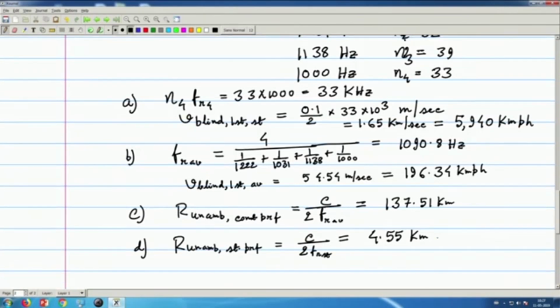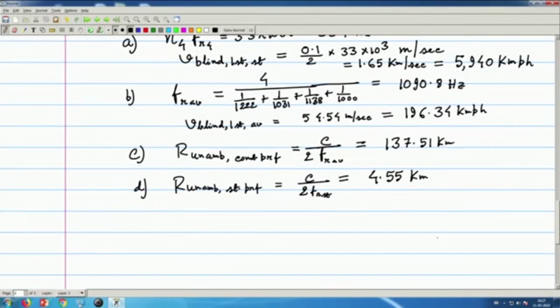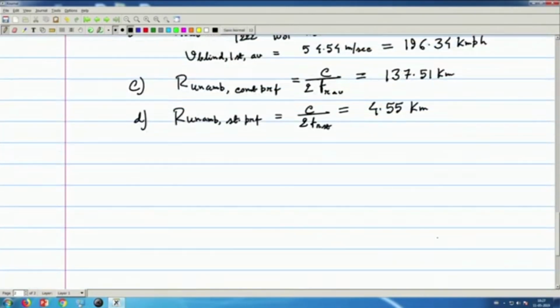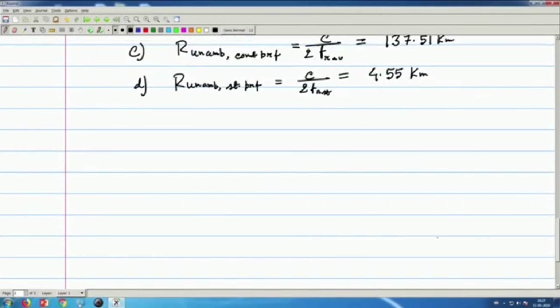Now, I will come back to the point where we left last time. You see, 4 PRF staggering is a common thing, but we do not know how to make the transfer function of the MTI filter if there are 4 staggering, because we have solved the problem for 2 staggering frequencies.